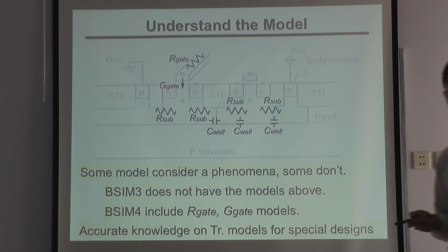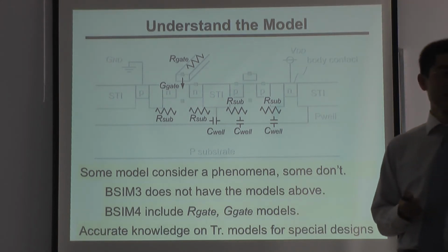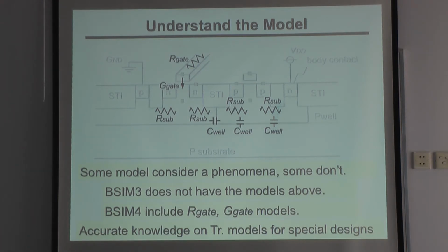So if you are interested in substrate noise, for example, you have to explicitly put this resistance on the schematic. And if you want to, for example, bias the PMOS body and dynamically control this PMOS body, these capacitors limit the breaking frequency. So you have to explicitly put capacitance values and resistance values on your schematic, because these are not included in the SPICE simulators.